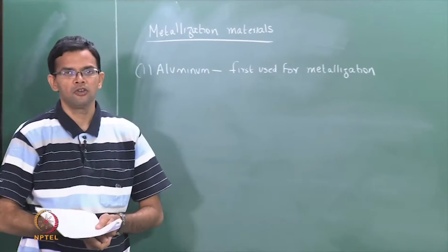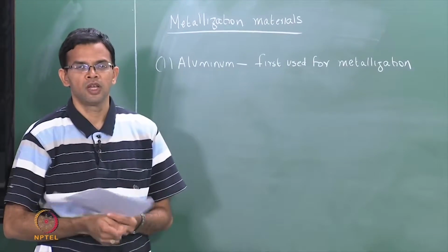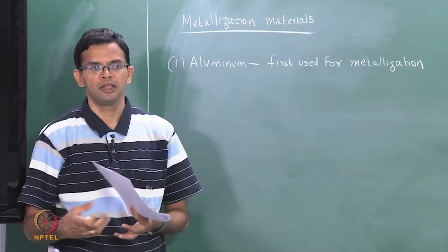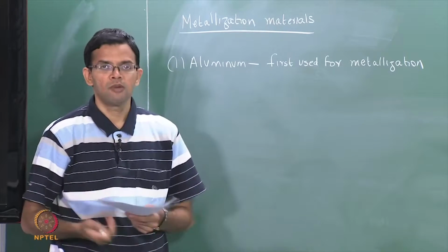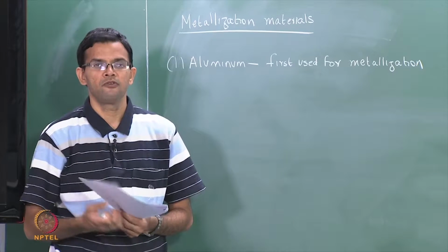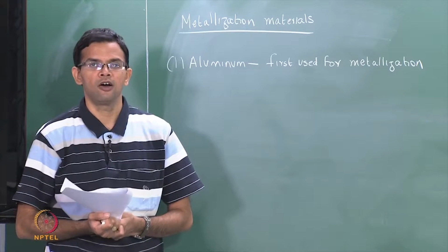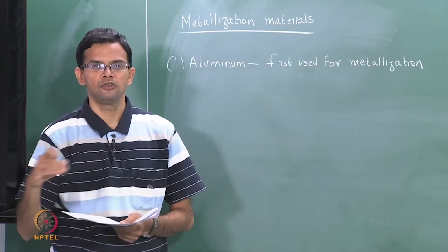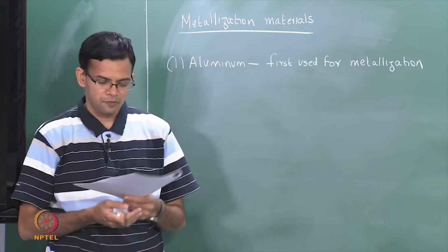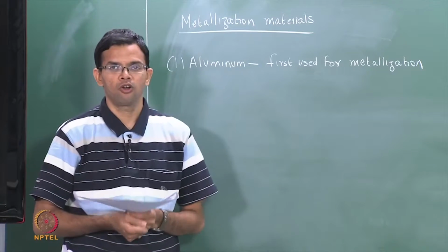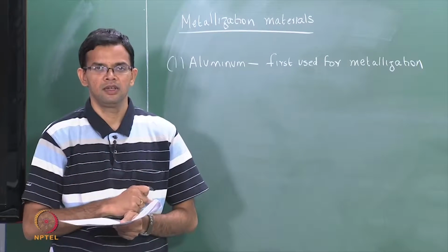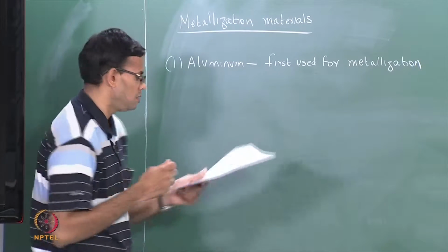So in the IC that was developed by Robert Noyce, aluminum was vapor deposited onto the circuit in order to make the metal connections. Some of the advantages of aluminum is that it is easy to vapor deposit. It forms a good bond with the silicon dioxide, because silicon dioxide is used in order to pattern the substrate in open contact holes. Aluminum also has low contact resistance, so by annealing the circuit you could form a good contact with silicon, and it is also easy to pattern.